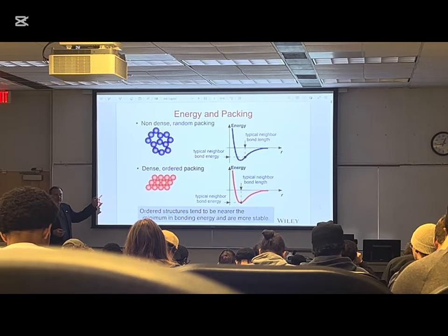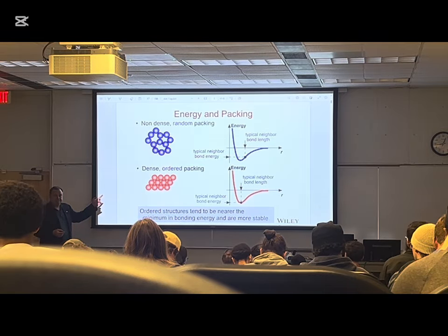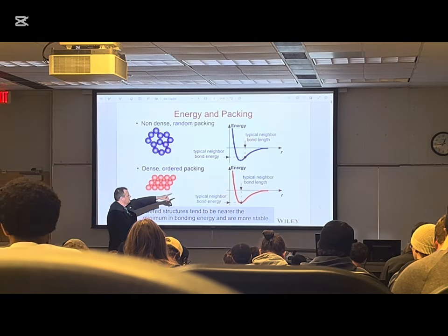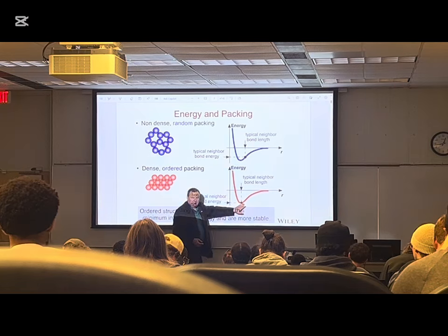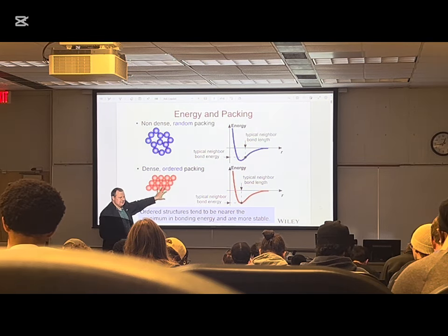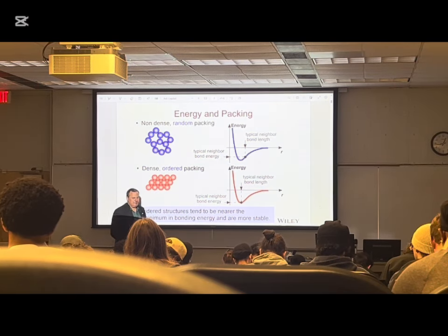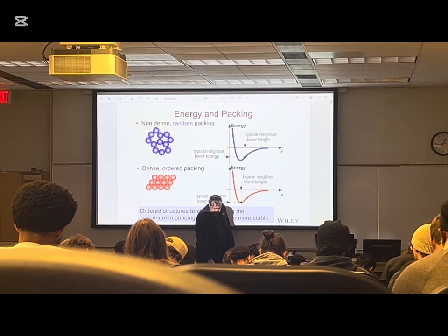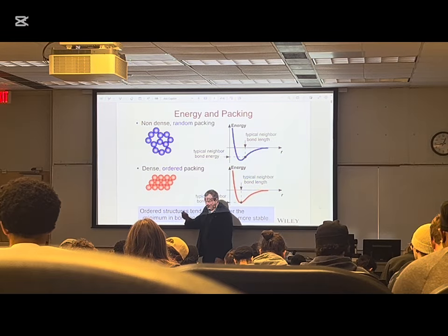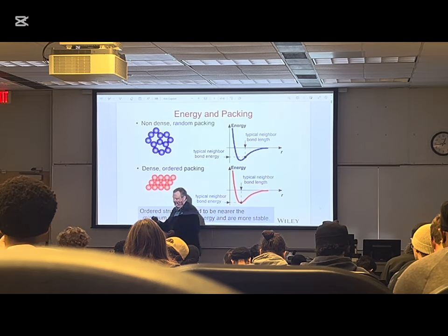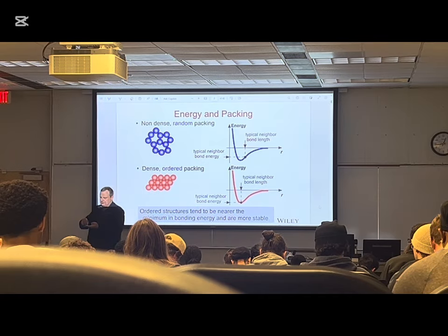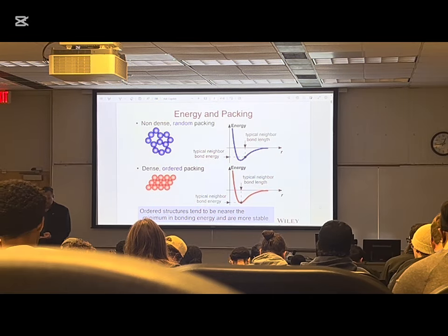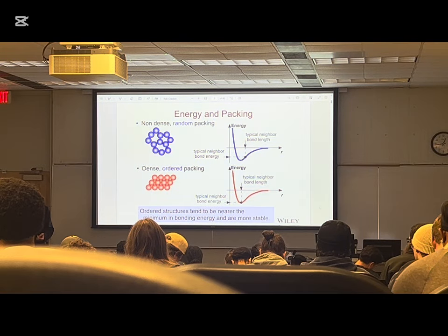Remember the well concept that we talked about last time? This is the energy, and when everything is neatly arranged in a close-packed fashion, and by the way, this is the close-packed plane. Plane means that I take these balls and I put them on a plane, and there's no better way to pack those balls.